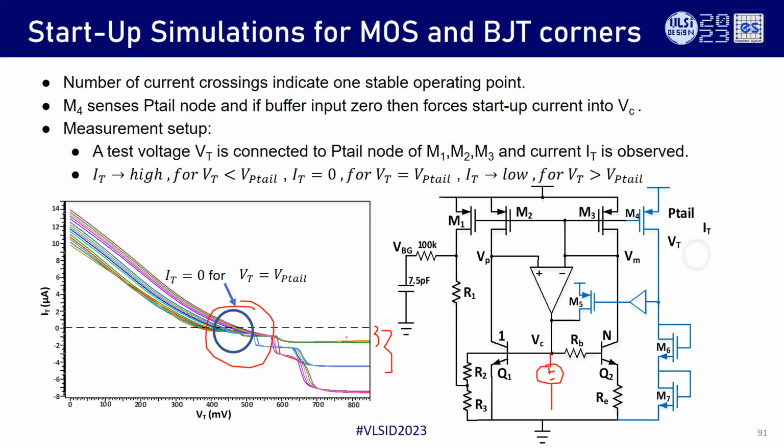So what will happen is, this is the bias current of the op amp. This has been run for 3 different temperatures. So this could be very low temperature corner, mid typical, and then maybe high. These are the bias currents, and this depends on the total op amp design. So that is an interesting recipe you can use, and by looking at this you can see whether it is biased properly or not.